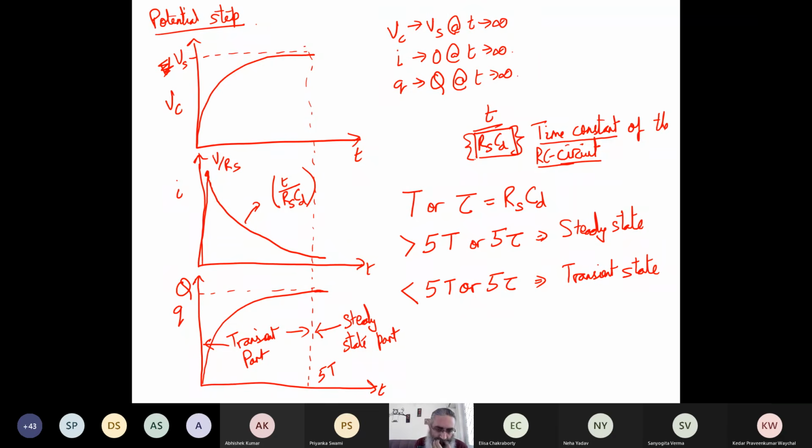Any questions so far? Subbu, I have one question. Yes, please. So when you say the double layer capacitance, I want to get some intuition here. The double layer capacitance is of the order of microfarads per centimeter square. Even if I assume something like 20 centimeter square, it's still microfarad order. And if the resistance is of the order of say 1 or 2 ohm, so the time constant is something like some microseconds, is it? Yes, milliseconds or microseconds. That's exactly what we are going to look at.